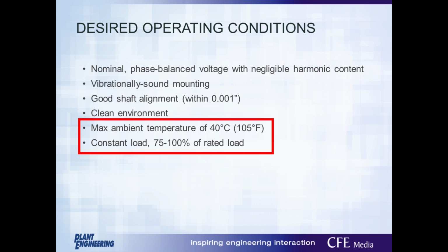First, let's talk about ideal operating conditions for your motors. Ideally, you'll need balanced voltage from your utility. For instance, if you have three-phase 480-volt supply at your location, those phases should be balanced to within at least 1% or better. The more out of balance your phase-to-phase voltage may be, the more detrimental to your motor's efficiency and also long-term reliability.